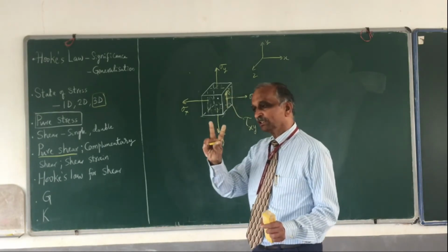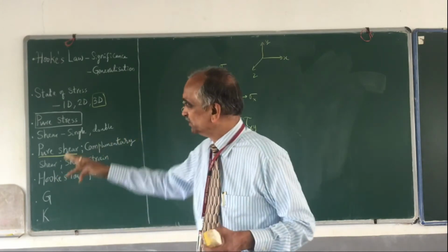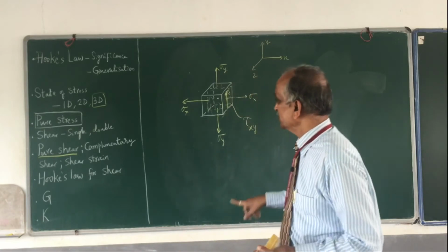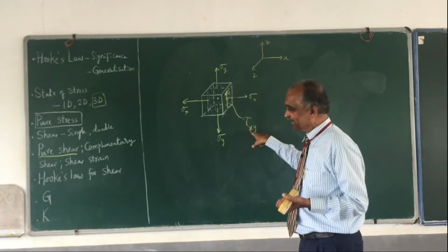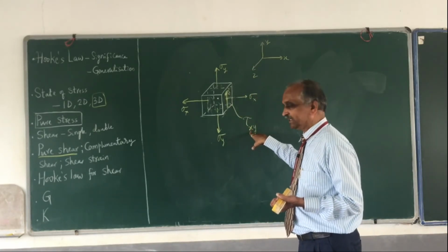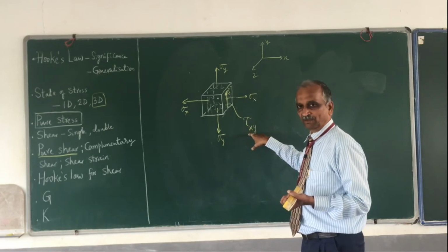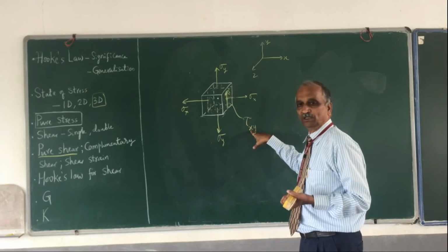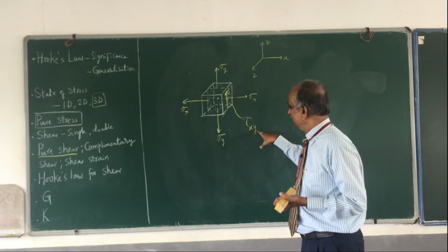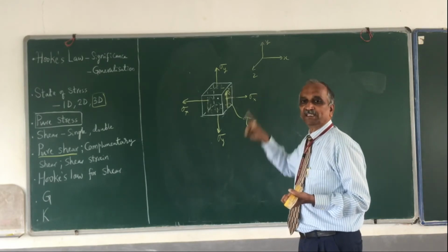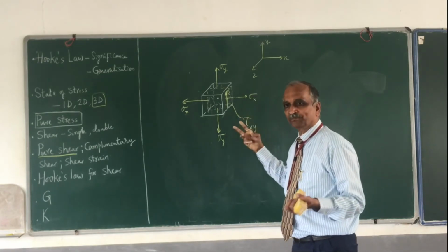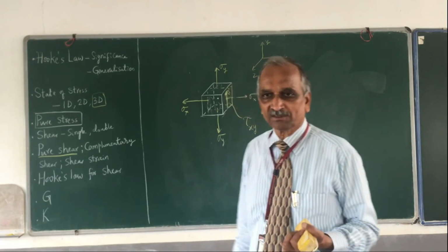Every shear stress shall be indicated in a state of stress with two suffixes. The first suffix shall indicate on what plane, the plane being perpendicular to the first suffix, and the second suffix indicates the direction. And similarly, why not two suffixes for the normal stresses?